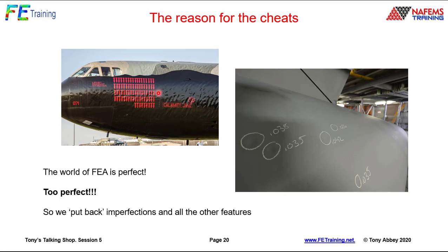Here's some cases. This Boeing B-52, it's well known for the ripples occurring in here. The story goes that originally it was just designed for like a 3-man crew, no ejector seats. Then by the time they bumped it up to whatever it is, 5 or 6 men and the ejector seats, you get these semi-diagonal tension fields, actually permanent ripples in the structure. So for buckling, we probably want to model those.